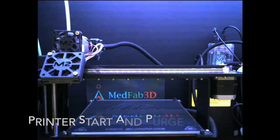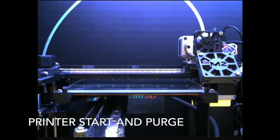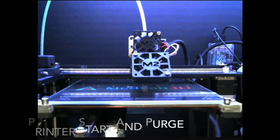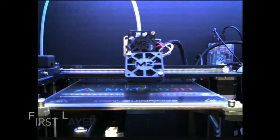This is video of the same 3D printer making the part in real time. And this is the start of the process, where you can see the printer move off the bed to the right, and it's purging material out of the extrusion head. And then it moves to a center position and it starts to perform an outline. And the outline is actually offset from the part. This won't be part of the part.